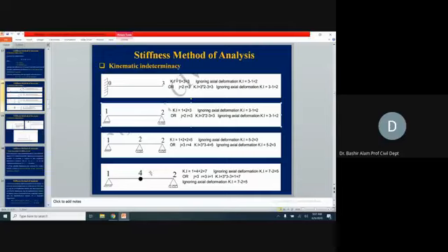And now let's discuss why we have at the hinge these 4 degrees of indeterminacy. This hinge is in the middle now. This structure is unsymmetrical. Let's say this hinge, instead of the middle, we push it to the left. Let's bring it to this 1/4 position of the total span. Instead of this, we bring it here. Now, if we load it, what will happen? It is going to deflect this way.